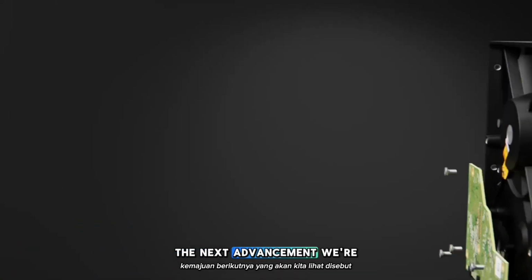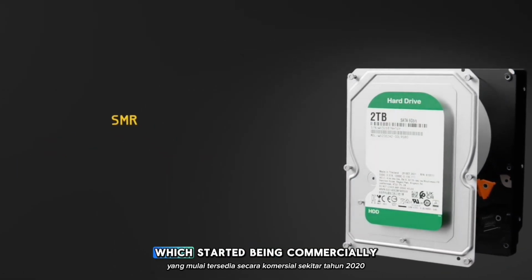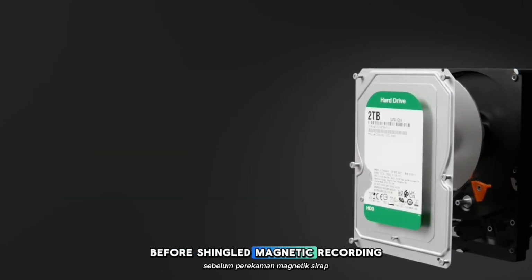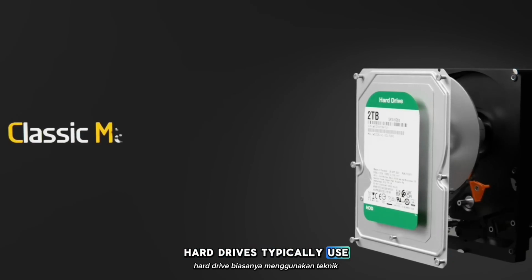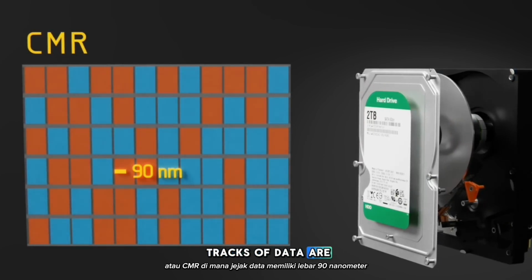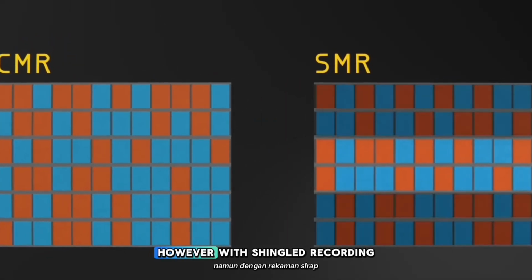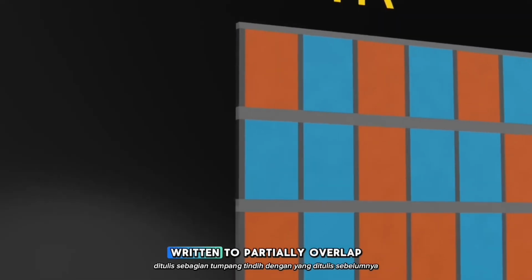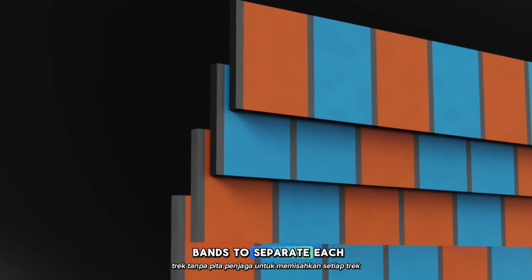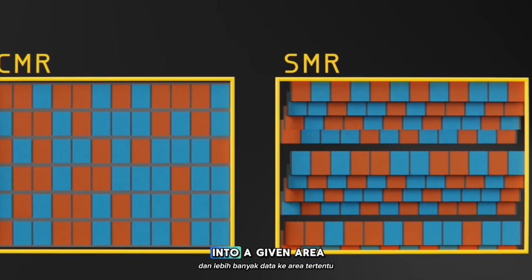The next advance we're going to look into is called Shingled Magnetic Recording, or SMR, which started being commercially available around 2020. Before shingled magnetic recording, hard drives typically used the technique conventional magnetic recording, or CMR, where the chunks of data are 90 nanometers wide and have guard bands on either side of the track. However, with shingled recording, the tracks are written to partially overlap with previously written tracks, with no guard bands to separate each track. Thus, we can fit many more tracks and much more data into a given area.